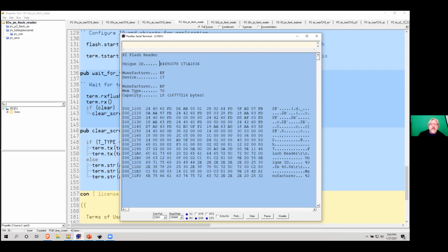Again, the nice thing about using the flash is we get a serial number for our devices. And with the laser tag company, they're actually very happy about that. They don't have to serialize them separately. In the P1 version of that project, there was an iteration of the board that had a 1-wire serial number on it because they wanted an electronic serial number. Later, it turned out we needed that IO pin so badly that we gave up the serial number, but with the P2, we don't have to because the flash has a serial number that we can use.